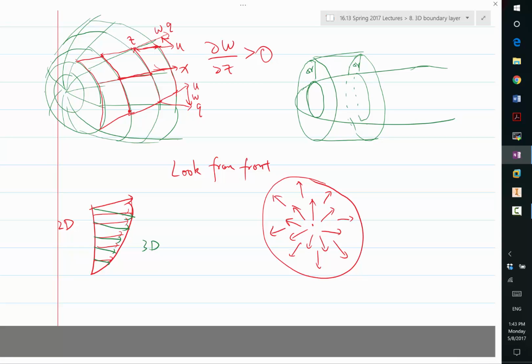So as a result, the growth of the boundary layer is a combination of two effects. One is the y velocity, the v, that advects the slower velocity upward. Another effect is the shear that, due to viscosity, brings the velocity down, even on the same streamline. So in the 3D boundary layer, the advective effect of thickening the boundary layer is less severe, or even opposite, because of the divergence in the lateral direction.